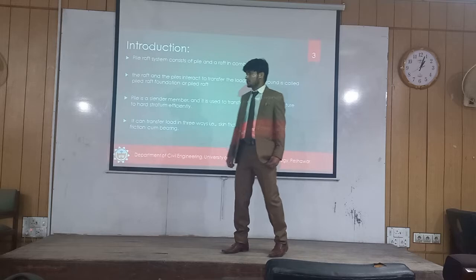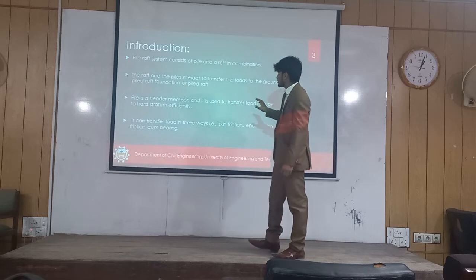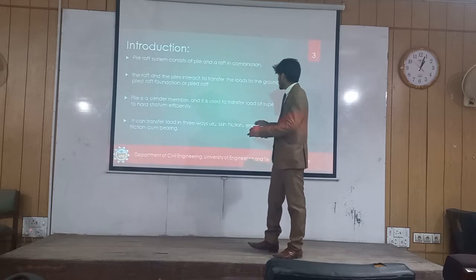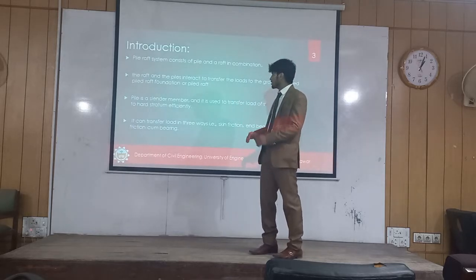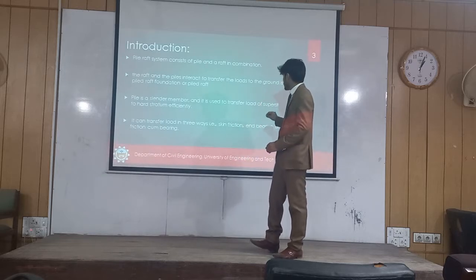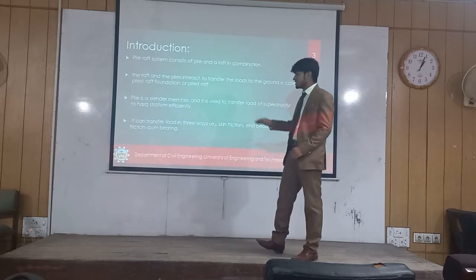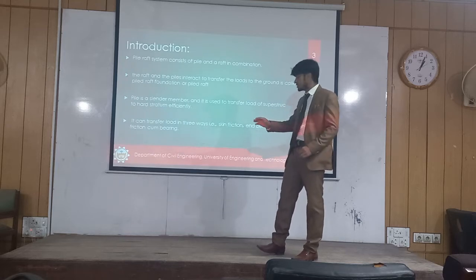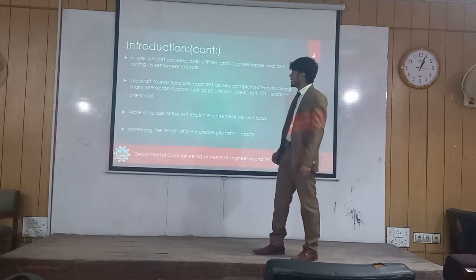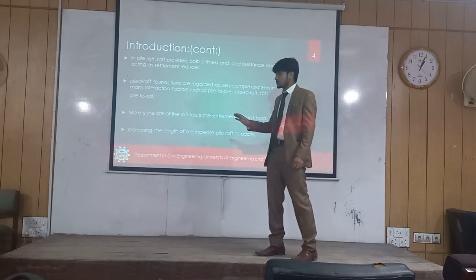Assalamualaikum. My name is Muhammad Zishan. My introduction: a pile raft system consists of piles and a raft in combination. When the raft and the piles interact to transfer load to the ground, it is called a pile raft foundation. A pile is a cylindrical member used to transfer the load of the superstructure to the hard strata efficiently. It can transfer load in three ways: skin friction, end bearing, and a combination of friction and bearing. The raft provides both stiffness and load resistance, and the piles act as settlement reducers.